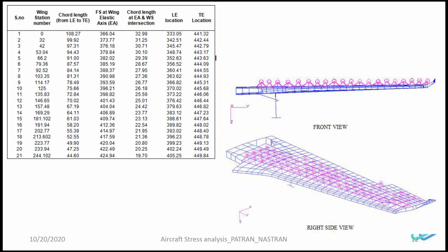It's also an interpolation element. So when we apply the load at the dependent node, based on the lengths, it would distribute the loading to the independent nodes.